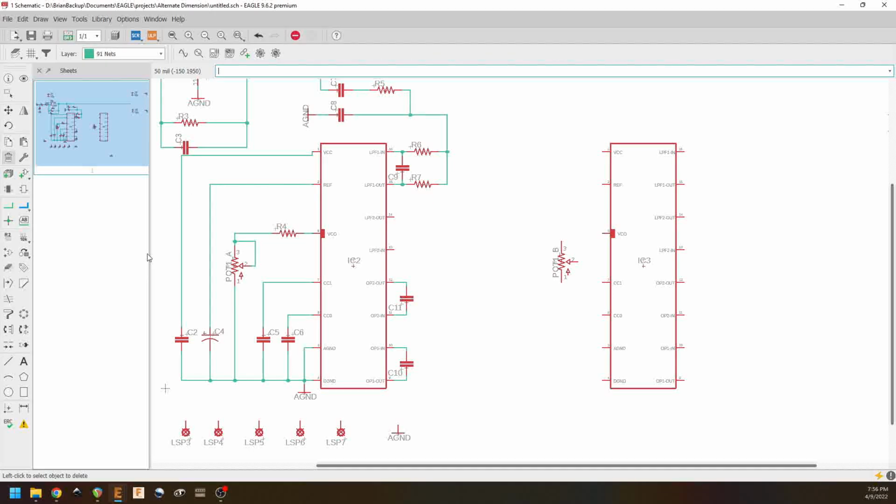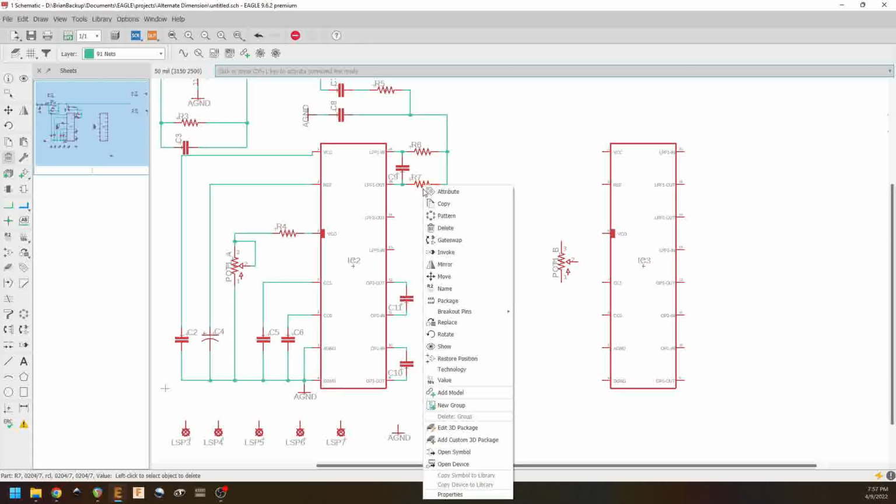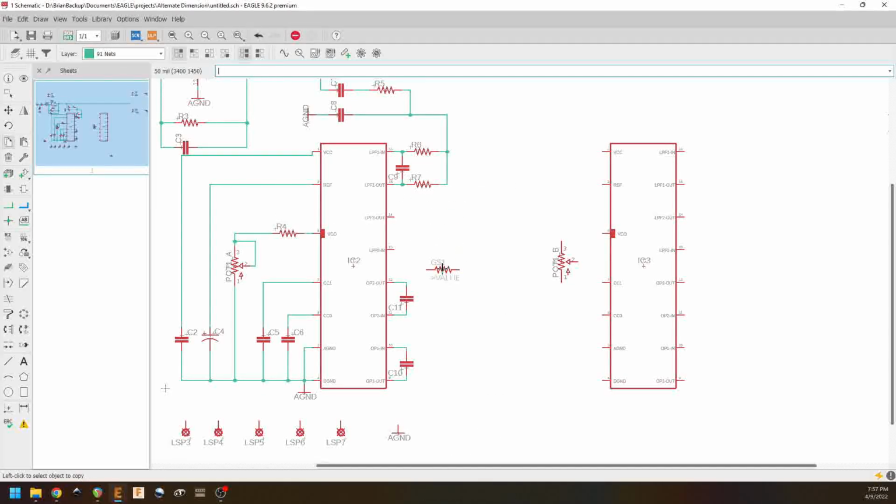And now, because pin 12 is our output, we're going to set up another multi-feedback filter on these pins. So we need to take our signal that's going to be our input to the op amp, which is going to go through a resistor here. It's going to go cap to ground.